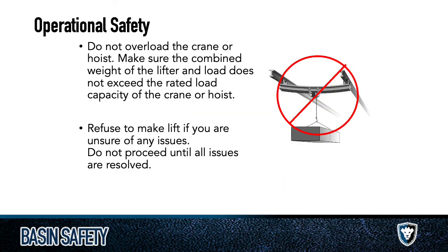So do not overload the crane or hoist. Make sure the combined weight of the lifter and load does not exceed the rated load. And again, I'm a big fan. It's more difficult with overhead cranes, right? It's not like, oh, let's get a heavier crane in here. It's installed. It's there. So I do recognize it's easier said than done, but my recommendation is make sure you're well below the weight capacity of the actual crane.